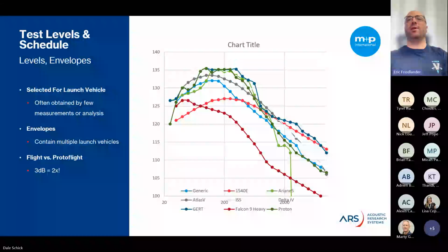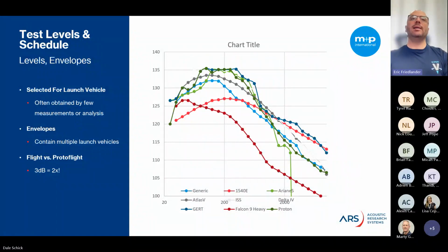The fairing environment also changes over the course of launch, but an acoustic test with a random uniform field is your best common denominator to capture the most stressful potential environment that could occur during launch. That's been the heritage approach to building confidence in that regard. One of the great things about being able to test in third octave is you can also envelope multiple launch profiles. If you don't quite know what you're going to launch on, you can take the loudest frequency from each of, let's say, 3 launchers, and make a composite envelope out of that. The upside is you're pretty much qualified on any one at that point. The downside is you are potentially adding additional stress and fatigue onto the flight hardware that might be above and beyond what we would see in flight. So there's always a trade-off there.